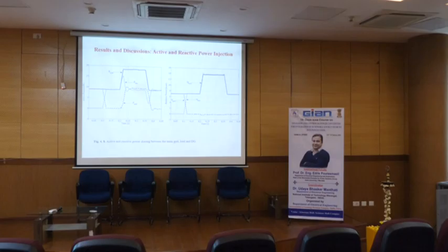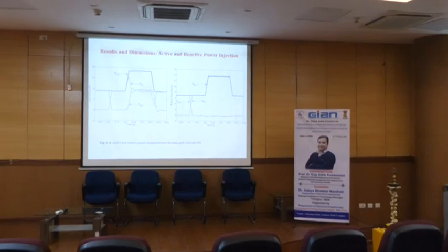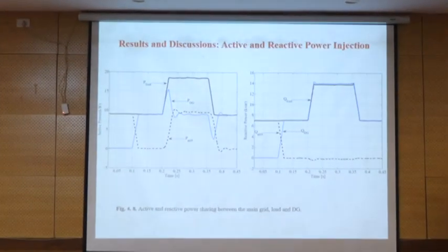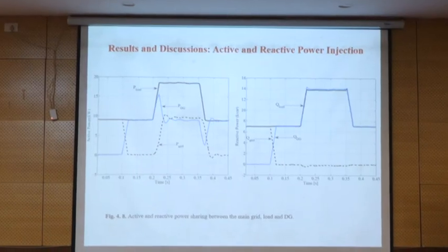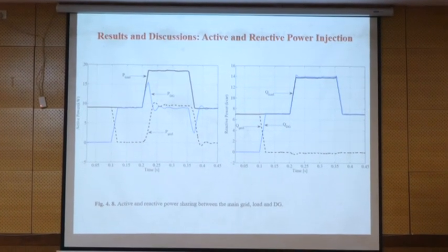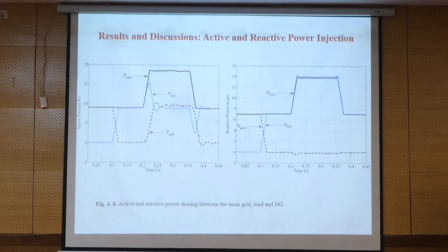Inner control. Linear control. But we are also using a PI controller here. One answer can be response time, because we also use the filter, and the filter provides a delay, and then the PI controller cannot follow it.